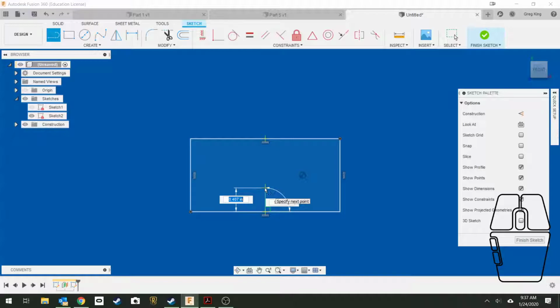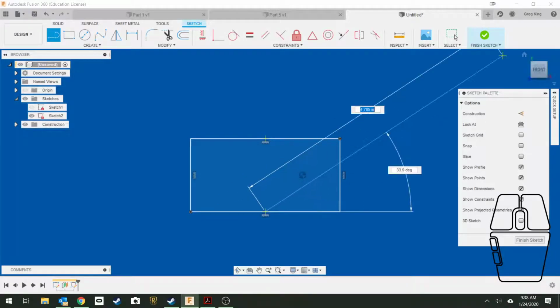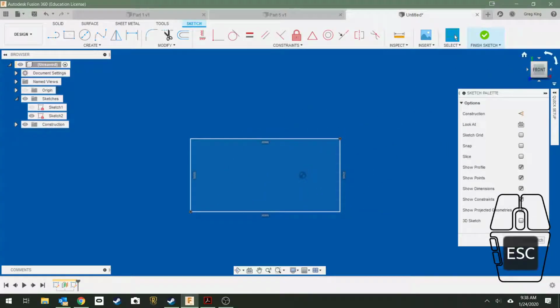You're looking at the sketch references, the page that I gave you. You have to look at the isometric drawing and kind of imagine what the bottom and the back would look like if they were drawn. Kind of draw a line with your mind. If you had it actually printed out, you could draw a line with your pencil on it. Draw a line with your mind, the bottom, back, to where the line from that triangle would come down, and measure up from there. Let me bring this over and show you what this looks like actually. So you can see it in the screen here.